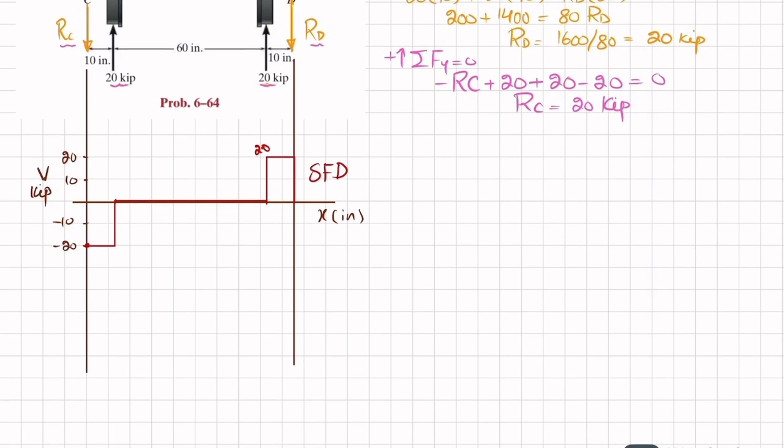Now by using this shear force diagram, we'll draw the bending moment diagram. Again you have a horizontal line that shows length in inch, and on the y-axis we will have moment in kips into inch. Let each division be 100, so minus 100, below is minus 100, so minus 200.